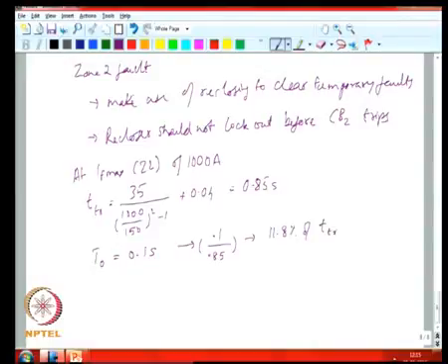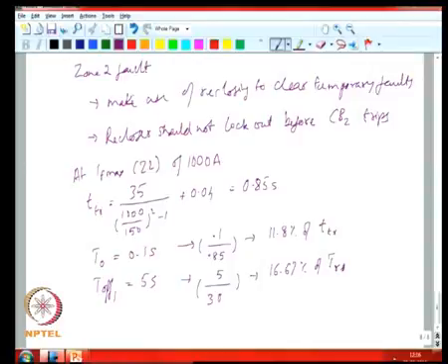So, it is about 11.8% toward trip at that condition, and then you have the first off duration T off 1 of 5 seconds, and the 5 seconds, in terms of the overall reset time for the circuit breaker, which is 30 seconds, means it is resetting by 16.67% of T reset. Obviously, it is not going below 0, so it now resets back to 0.